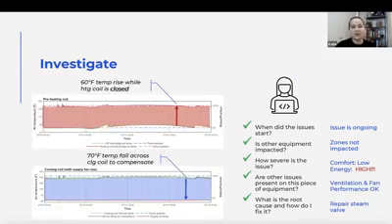So let's look at how severe the issue is. So again, we look at those pesky coils and those pesky valves, and we see that our preheating coil valve is 100% closed. It's not open at all. And we're seeing a 60-degree rise across the coil. We would not expect that to happen. But on top of that, when we're looking at severity and how much of an impact this has on energy consumption, we see that the coil that comes after it is then saying, wow, I have 140-degree air coming at me, and I need it to be 55, and I am open 100%, and I still can't get there.